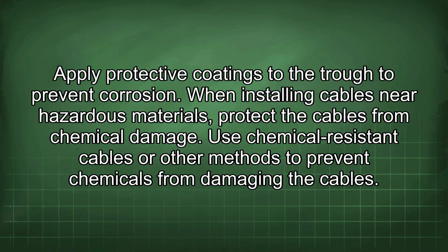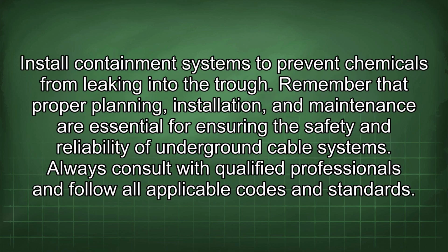When installing cables near hazardous materials, protect the cables from chemical damage. Use chemical-resistant cables or other methods to prevent chemicals from damaging the cables. Install containment systems to prevent chemicals from leaking into the trough.